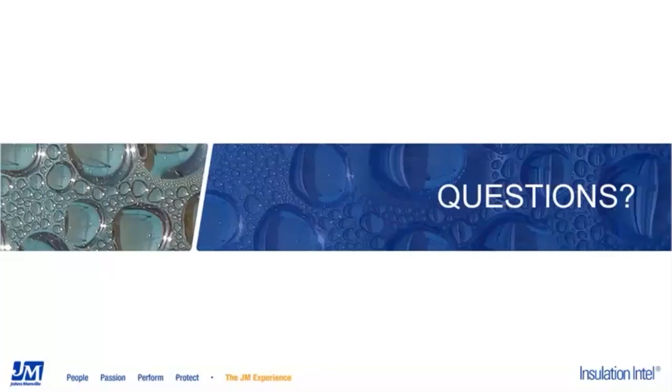And so you want to maintain that continuity around all your supports, hangers, etc. The first thing I would recommend is to use external supports. So use pipe supports that do not pierce the insulation system. Use a pipe support that the entire intact insulation system rests upon, so you don't have any kind of penetration and no need to worry about sealing a penetration.